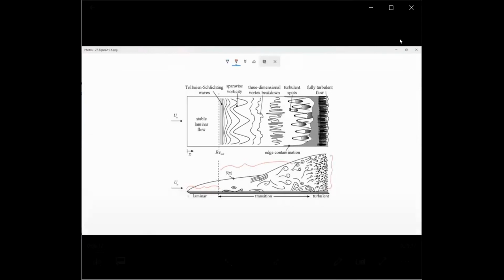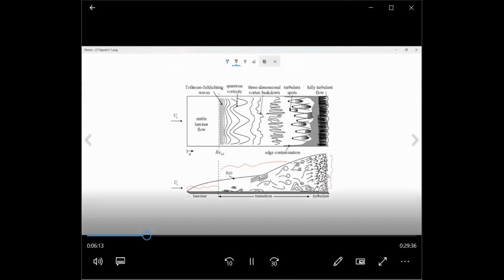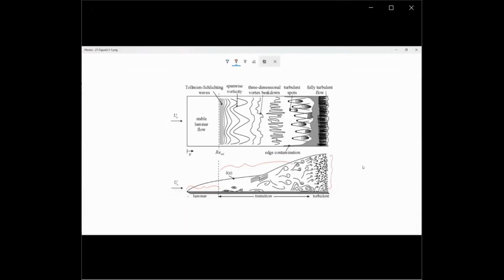When the boundary layer turns turbulent, the velocity profile becomes significantly different. Since the velocity profile becomes significantly different, all the related parameters like delta, delta star, theta become different. The boundary layer becomes much thicker, and the surface friction coefficient becomes very different. Therefore, the drag estimations have to be adjusted, and will be significantly different than what we have in the laminar case.